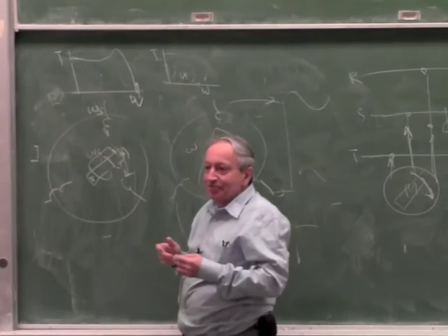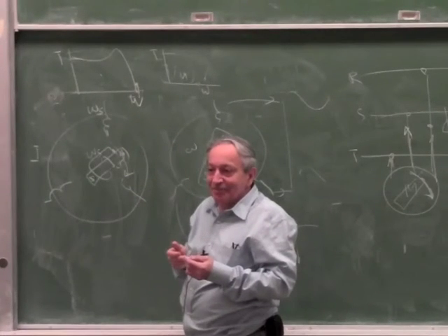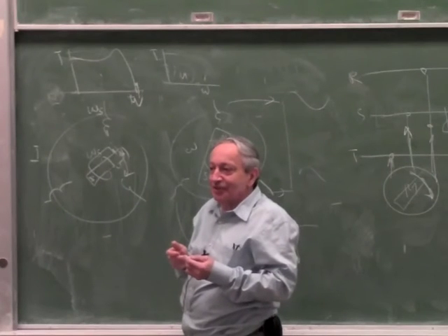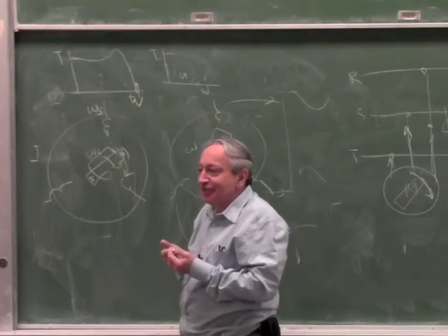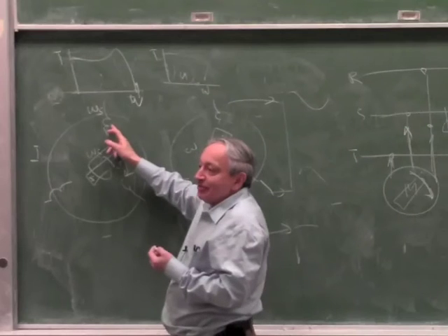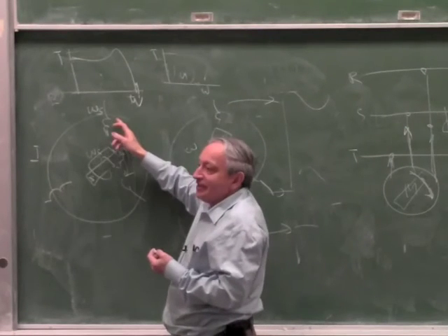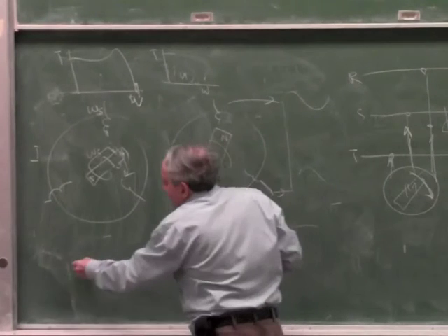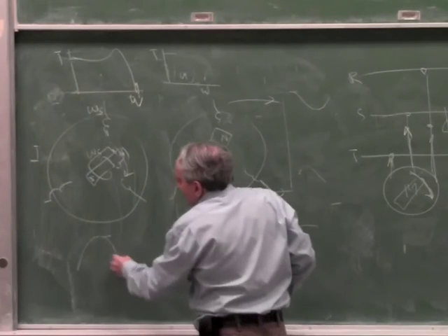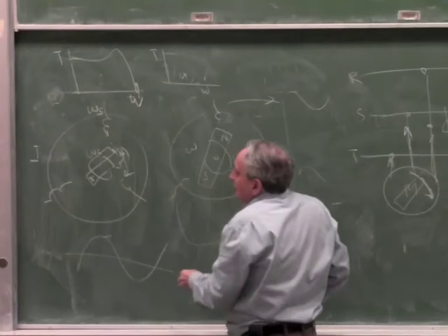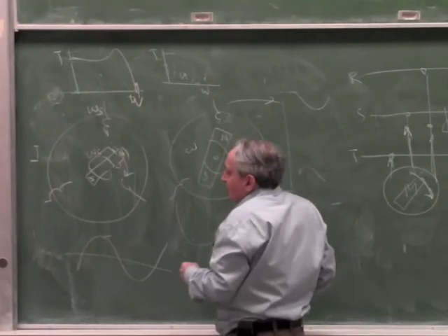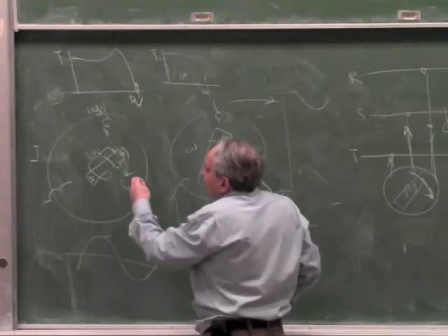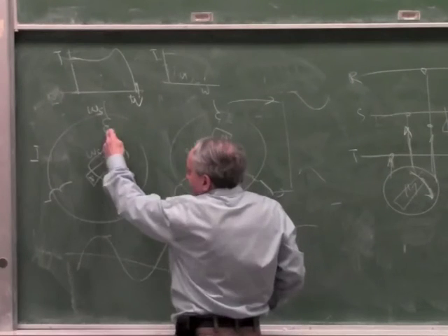Then there is a slip, there is induced current, but the induced current is trying to generate an EMF which is actually leading in phase, and because the EMF is leading in phase, the current flows backwards. So imagine if this is the input voltage, and you manage to turn this faster, and momentarily there was an EMF which was higher than this voltage.